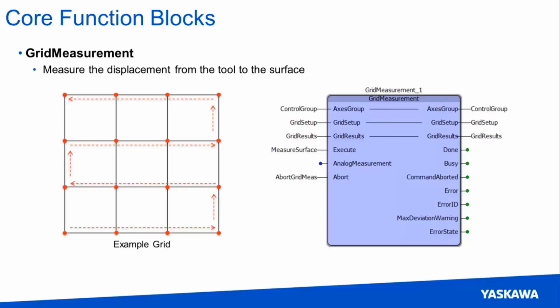One thing to mention is you can set the resolution specific for X and Y. So if you have a rectangular bed, you may want to take more data points along the Y-axis. So you'd want to set that to maybe 8 and your X to 4, giving you more data points along the surface, but at a uniform spacing compared to the X.